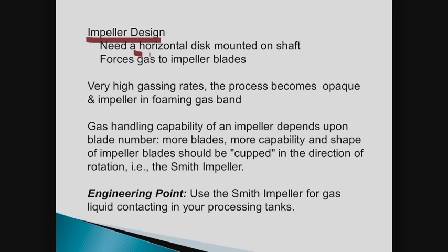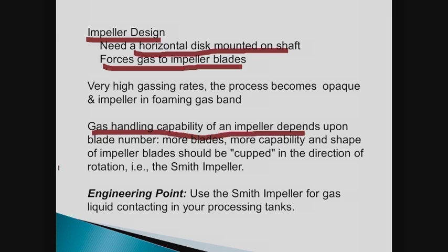So, impeller design, you need a horizontal disc. This will force the gas to go out to the impeller blades. Gas handling capability depends upon the impeller blade number. More blades, the better, up to a certain limit. You want it cupped in the direction of rotation, and you want to use the Smith impeller.